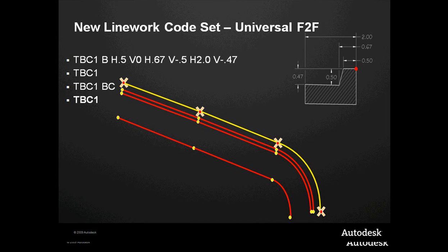Absolutely. The question is, can I start at the flow line and have it go left and right? The offsets, as we put them in, if they're positive, they'll go to my right in the direction that I'm walking, and negative, they're going the other way. So just add the values and we can go to either side.